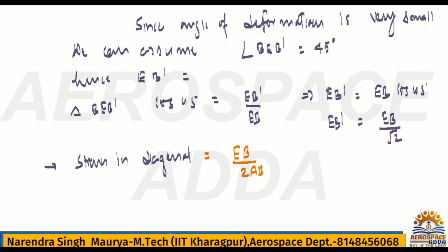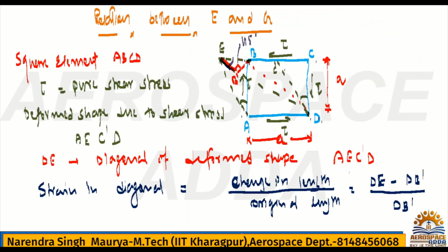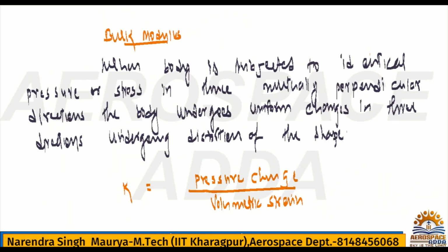Now also you can see here, because of 1 by 2, you just take one side, this is nothing but EB divided by AB. Now check what is EB by AB. It will be very clear. For this angle, I am giving phi. I told you both angles will be the same angle, and this phi is what I had given for shear strain.